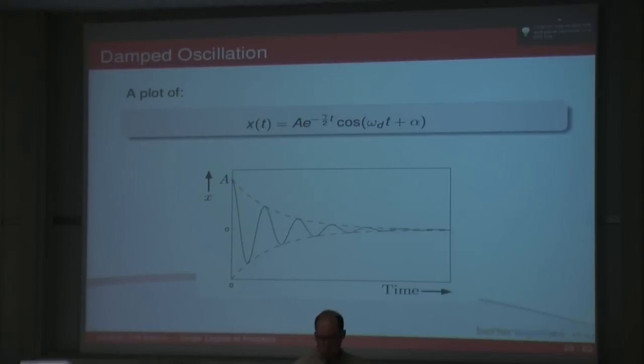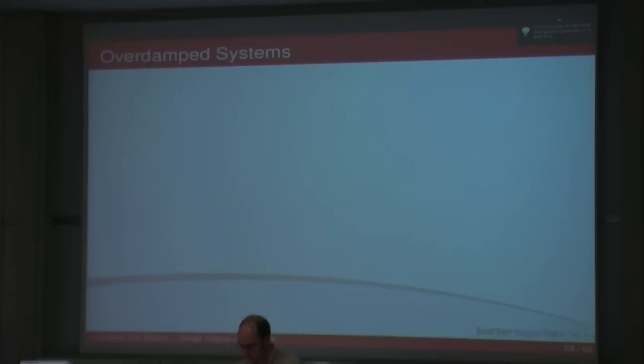Okay, so, well, what have we got now? Well, that was the case for underdamped systems, okay? Where omega naught squared minus gamma squared upon 4 is greater than 0, okay? What happens if that term is less than 0? What happens if damping is so much that that gamma squared upon 4 ends up being greater than your natural frequency? But obviously that solution is nonsense, isn't it? You'd end up with a negative frequency.